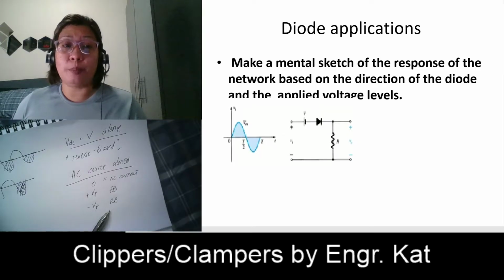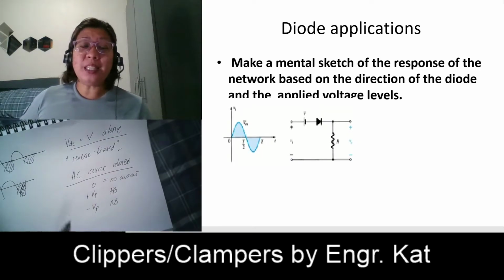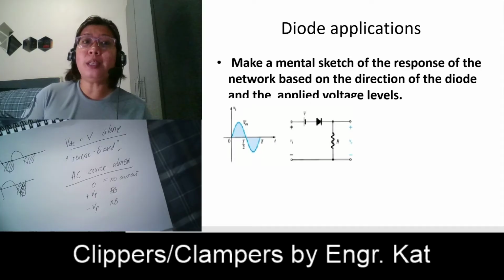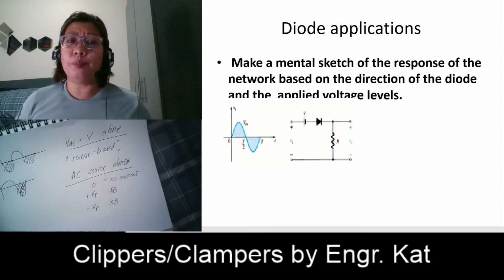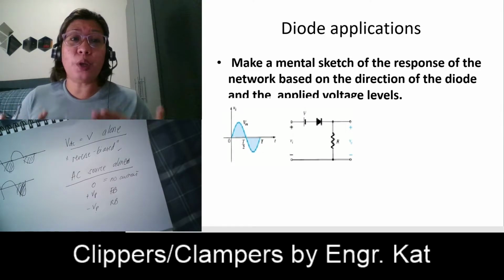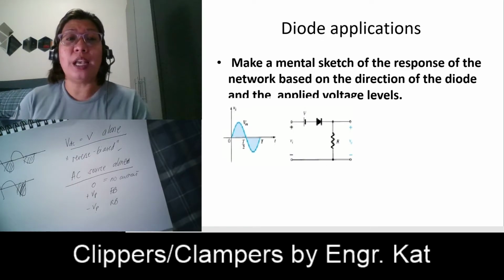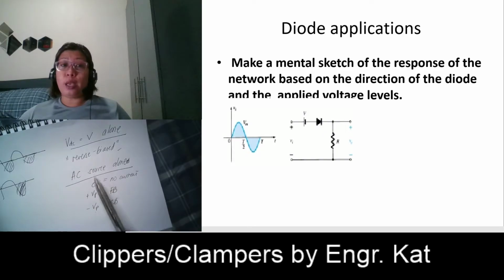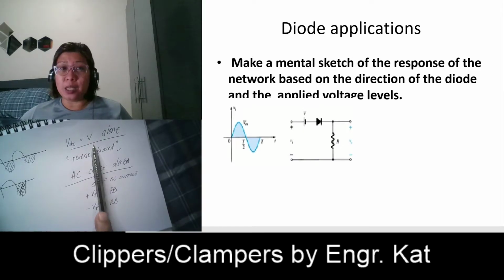can be reverse biased. Now, it doesn't happen that it is DC alone or AC alone. All the time, they go together. So once you turn on your circuit, it consists of the positive half and the negative half. So what do we do? If they are together and your AC source is 0, then we can say that your diode is reverse biased. Why? Because of the DC source. This is reverse biasing your diode.